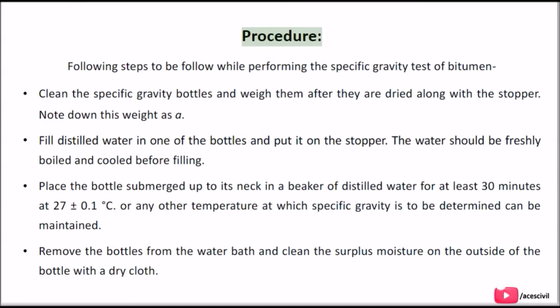Procedure. Following are the steps to be followed while performing the specific gravity test of bitumen. Clean the specific gravity bottles and weigh them after they are dried, along with the stopper. Note down this weight as a.